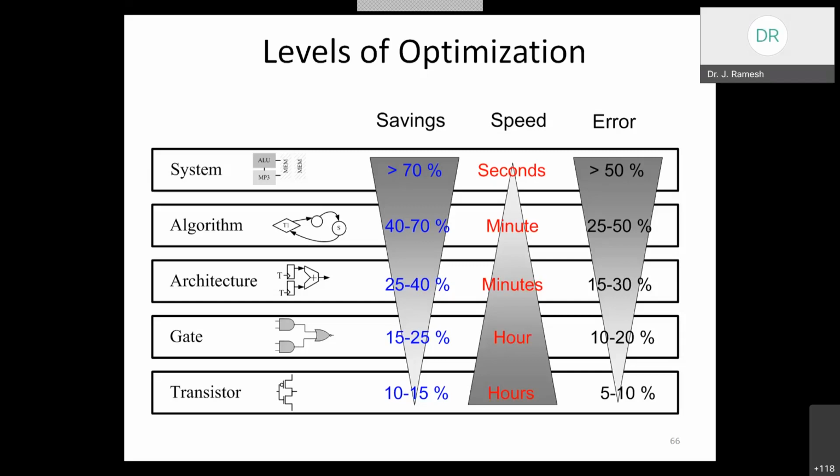So in between the data processing elements, we can introduce the registers. By introducing these registers, we can reduce the power consumption. The placement of registers, that is the location of registers, can also be distributed or changed and then analyzed. That concept is called retiming.